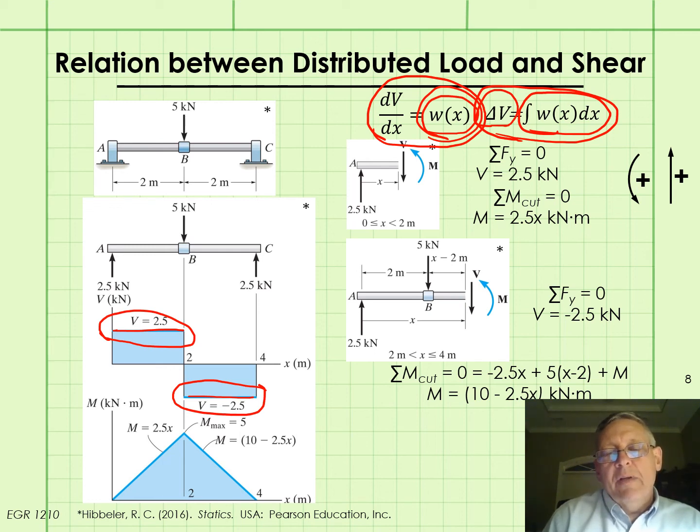We're going to do the moment relations in a second here, but it can help you construct the shear diagram, especially when you have lots of things going on the beam, where you have distributed loads, you have concentrated loads, and so on. So you can imagine if you have multiple concentrated loads and moments applied and distributed loads that are changing, you can end up with multiple segments of beam to analyze, and that can get very tedious.